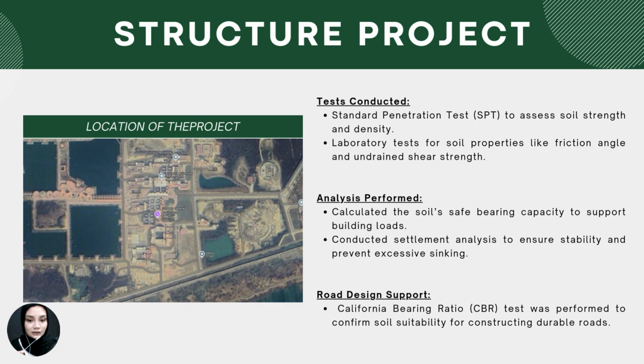Next, let's talk about the specific technical aspects of the project. Several critical tests were conducted during our investigations. These include the standard penetration test to evaluate the soil strength and density, and laboratory tests to analyze properties like friction angle and undrained shear strength. Using this data, we calculated the soil safe bearing capacity and conducted settlement analysis.